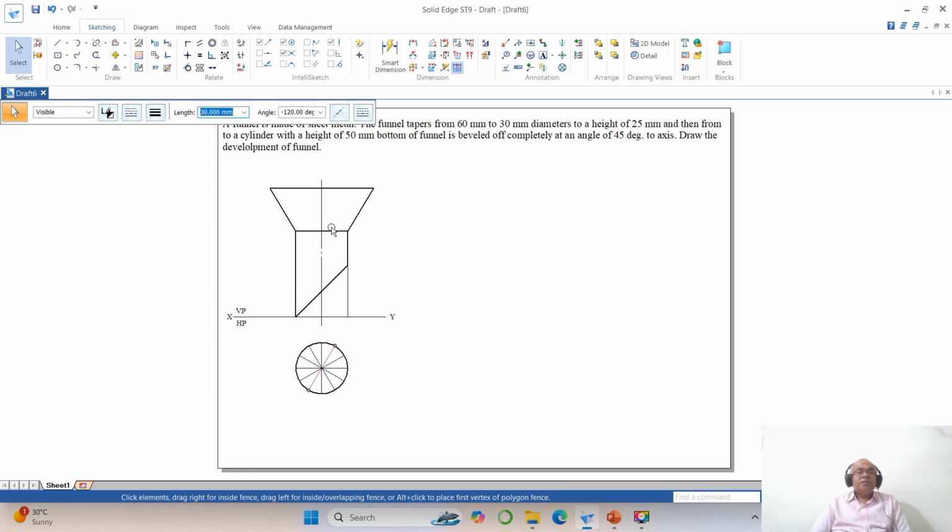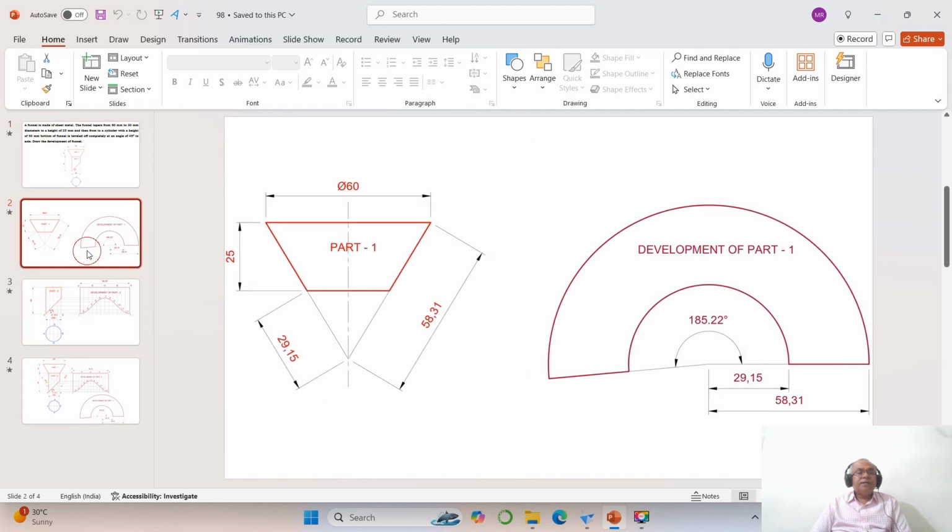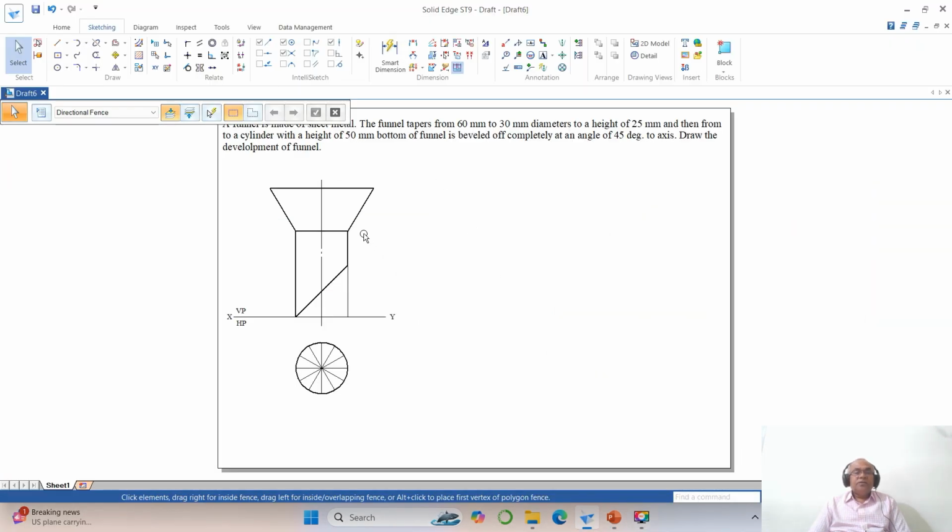Now once you do that, here you need to create this figure which is 185.22, okay. Now I want to get this particular part 1, so to do that, I will extend this object, wherein I will just go to extend to next. Now you go to split this line till here and split this line till here, then go to select by holding the shift key, you remove these two, make it 0.05, okay.